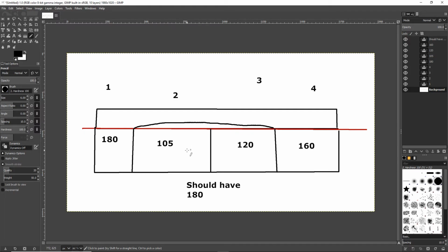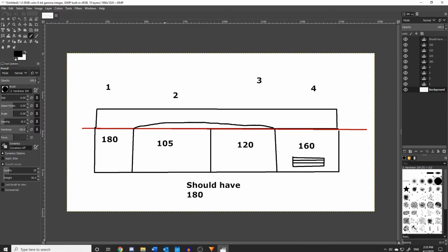And the fact that you find 2 of them next to each other that are very low is indicative of this. If they were all 160, I'd be like, that's not that bad, because I have a piston in here, and he's got 1,000,000 miles on him, and I know those rings are worn out. If the customer was really worried about it, we could rebuild the engine. If all 4 of these cylinders had a number like 105, that means that these rings and pistons are worn slap out, right? If it's even across all 4, we have to think of it that way. But in this one, we found just these 2, so that's where we're leaning.